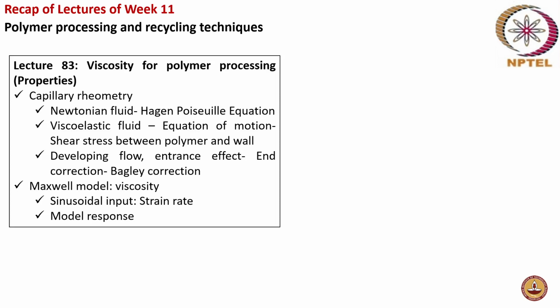The next lecture was on viscosity for polymer processing. So here capillary rheometry was discussed in detail. And then the Hagen-Poiseuille equation and what happens for a Newtonian fluid, whereas in case of a viscoelastic fluid, you don't have a Hagen-Poiseuille equation, whereas you have to use the equation of motion. And then the developing flow, entrance effect, and the Bagley correction were discussed.